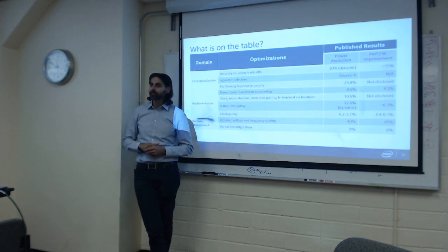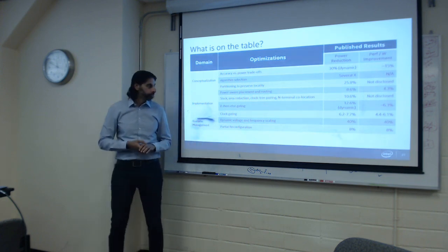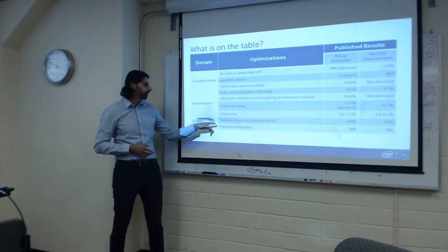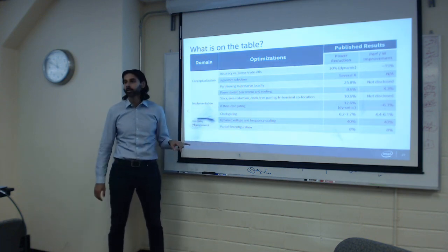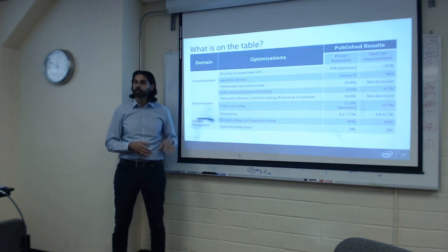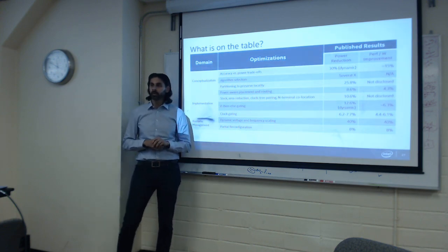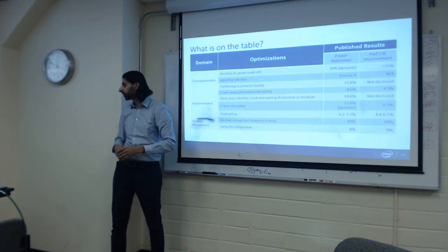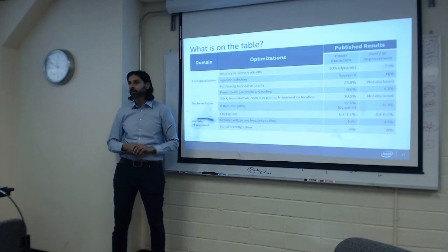Would you say that if you're working on a power reduction technique, you should be targeting dynamic power? Is static still dominant, or is it just a mix? I think the biggest knowledge is this runtime management, right? Taking advantage of the inherent knowledge of the application and looking at the actual trade-off of performance and power for that application. I think that's probably the biggest advantage we have, and according to Tom's research, that was the biggest lever that we found.